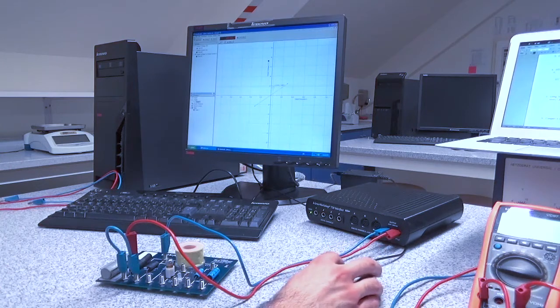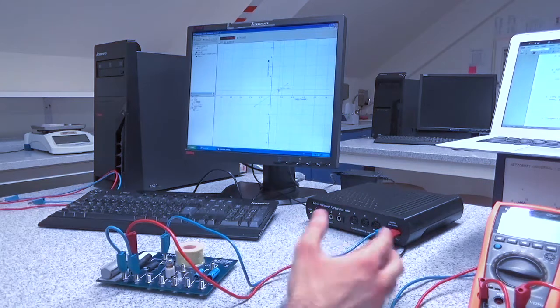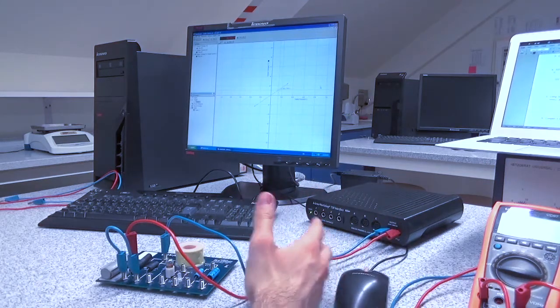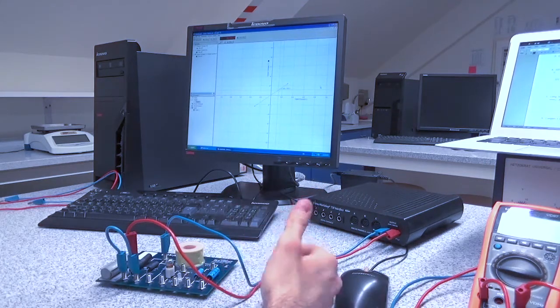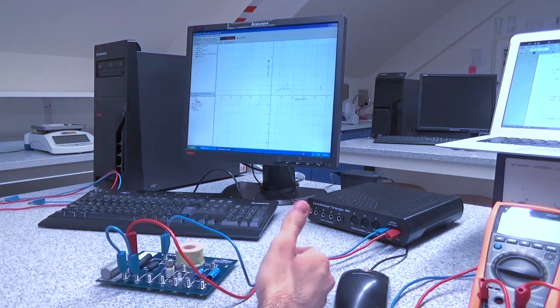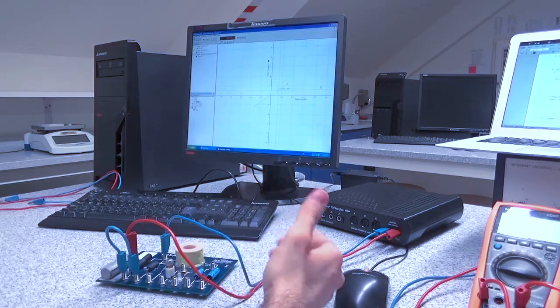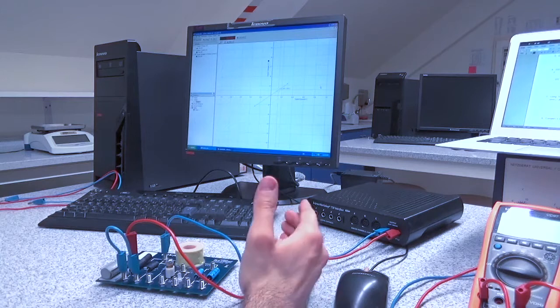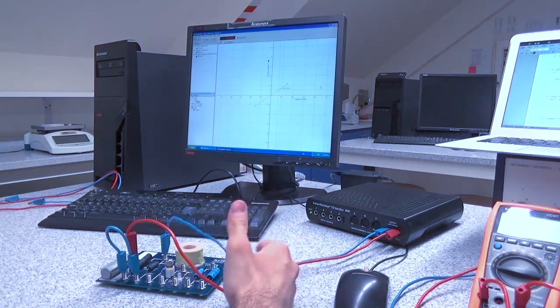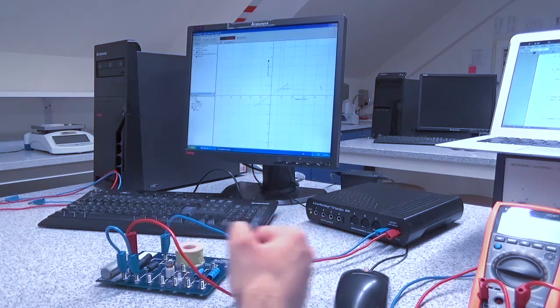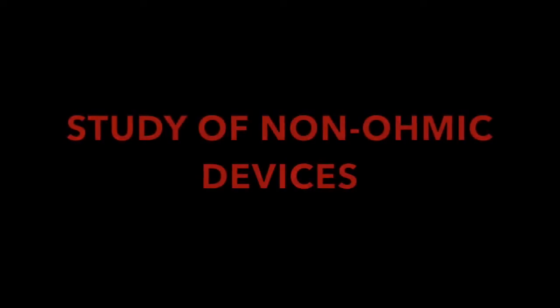So in a similar manner, you pick 4 different points for the voltage and the current, and then you apply linear regression in order to solve for the slope and the error on slope. And later on, you compare the value that you obtained for slope to the nominal R equivalent that you have obtained for 10 ohm and 33 ohm being connected in parallel. That would be for the second part of the experiment.